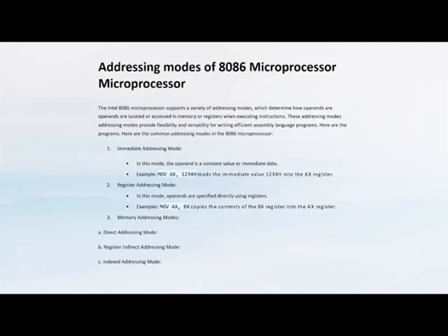Now, immediate addressing mode. In this type of addressing mode, the source operand is 8-bit or 16-bit data. The destination operand can never be immediate data. For example, MOV AX, 2000; MOV CL, 0A; MOV AL, 45; and MOV AX, 0000.